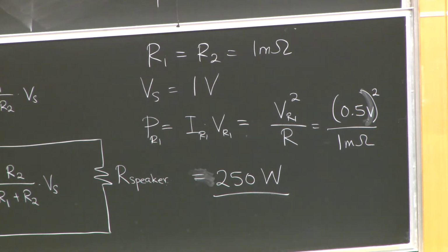So this is the downside, right? The price that I paid for being able to divide this voltage by 2 with a small load resistance, meaning my speaker, is power. And we'll see in about a week how we can deal with that without this voltage divider circuit. There's actually a better way of doing it, okay? But this is basically an example of how we can use our knowledge of voltage dividers and parallel equivalent resistances to solve a circuit like this. Cool.